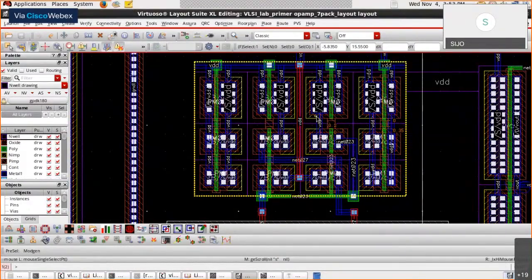Yeah. So here also you can see in the middle, we have 4 transistors. Since it is having almost 4 times the width of NMOS, I was able to make use of multiplier 2 for each device. So I have 4 devices to be matched. And I also have used dummies, which are surrounding all those things.